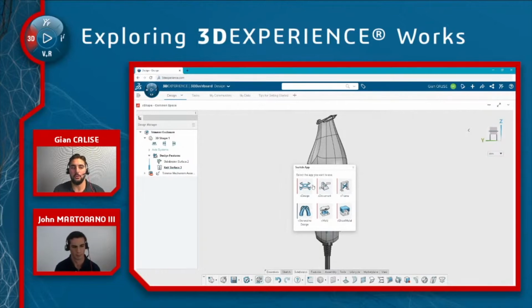Well, you might have noticed before that we had a rod going through part of that shaft connector. So that's kind of what restricted it from moving up and down. So the only advanced mate we actually needed to use was that slot mate that you saw us put in. Everything else was either coincident or concentric, which coincident, if you don't know, is just taking 2 faces and making them touch. And concentric is the same thing, just with circles, just lining up the center points of circles. So that's most of what the mates were in this entire assembly. And I think that the slot mate might have been the only advanced mate in this entire assembly. So really keeping it nice and simple.